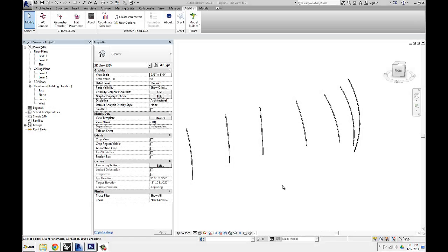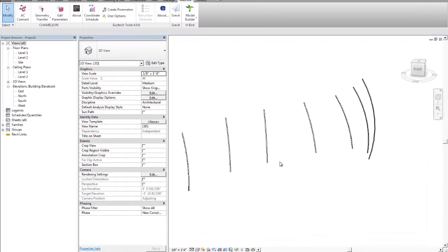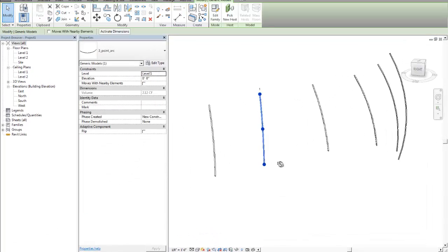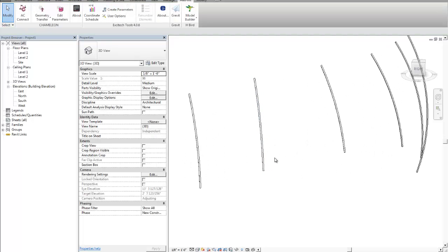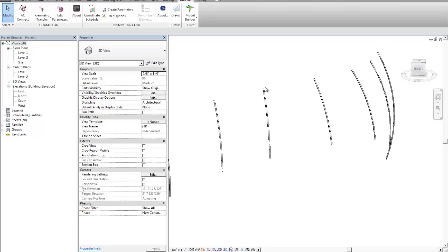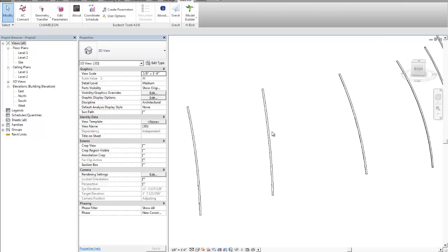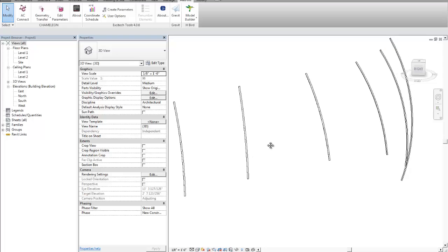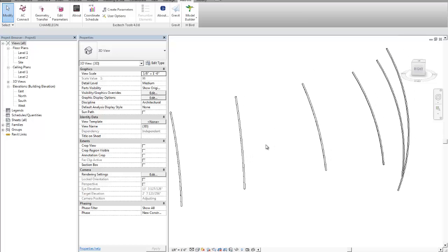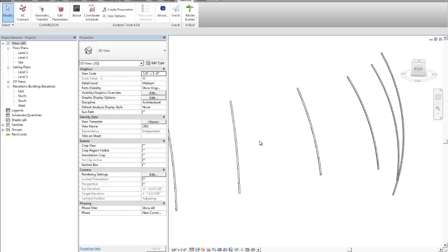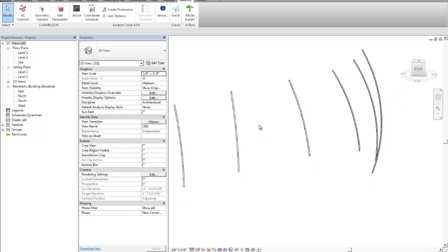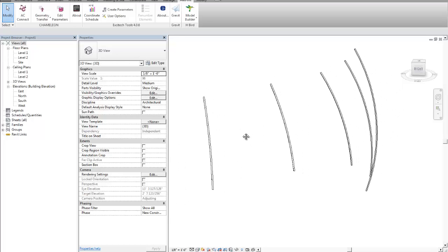Alright everyone, in the previous video I explained how to transfer that geometry that you see on the screen right now, which is basically a 3-point arc. I showed you how to make a Revit family. In this one we're going to work on a little short stubs. There will be a different type of family, and I'm also going to add a small wrinkle to the process by exporting some parameters for each one of them that we can later use in documenting it.